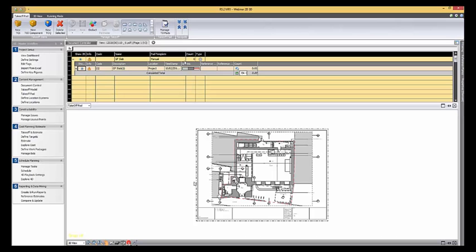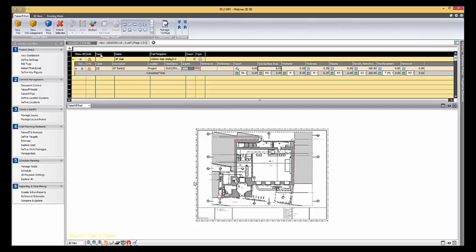So this is a set of rules and formulas which allow me to easily fill in things like volume and rebar tonnage just by measuring one thing. So I'm going to start by measuring the top surface area, and then from there I'm going to get some volumes and some reinforcement as well.